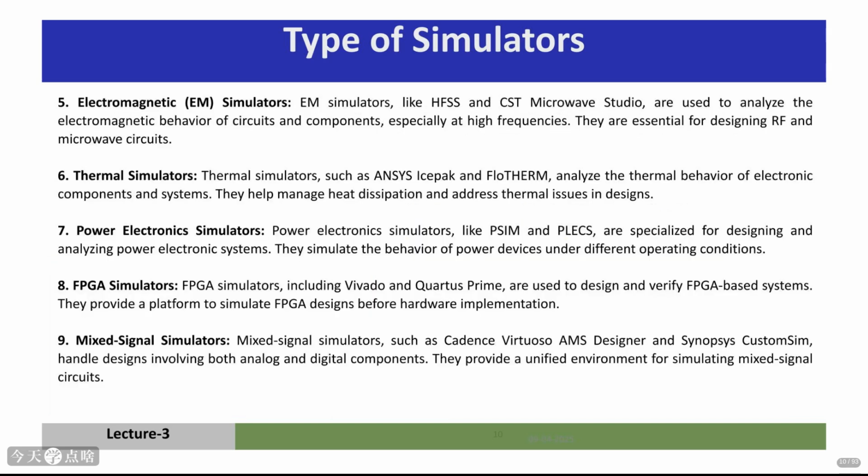The list goes on. Electromagnetic simulators like HFSS or CST Microwave Studio are vital for high-frequency RF and microwave circuits, analyzing electromagnetic waves and radiation. Thermal simulators like ANSYS IcePack help manage heat, which is a huge concern in dense integrated circuits. Power electronics simulators like PSIM or Plex are specialized for circuits dealing with high voltages and currents.